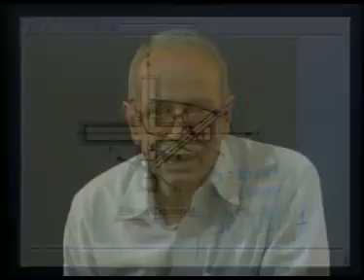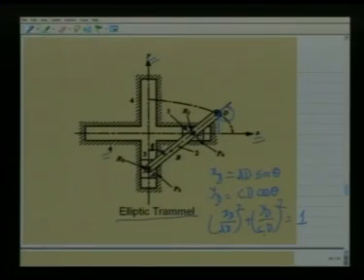It must be pointed out that there are 3 points on this rod AB which are exceptions. Namely, this point A, which generates a vertical straight line because of this prismatic pair. Similarly, this point C, which generates a horizontal straight line because of this horizontal prismatic pair.